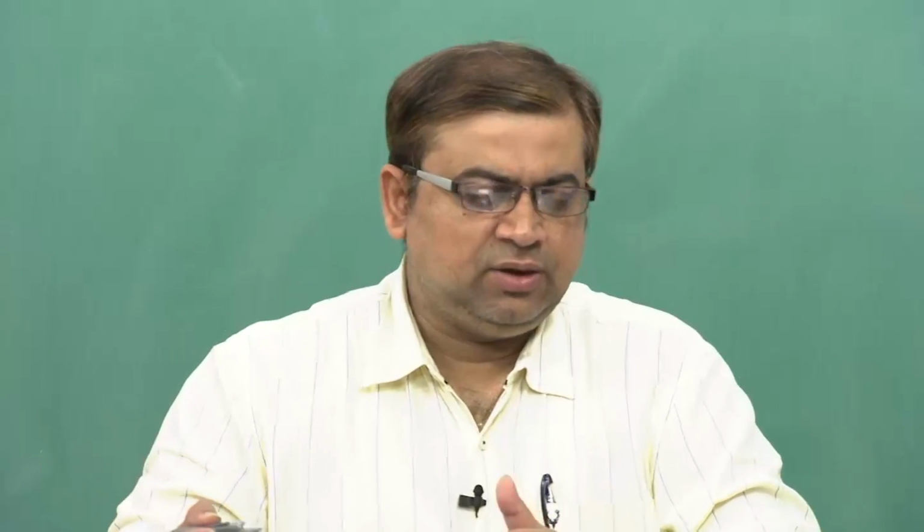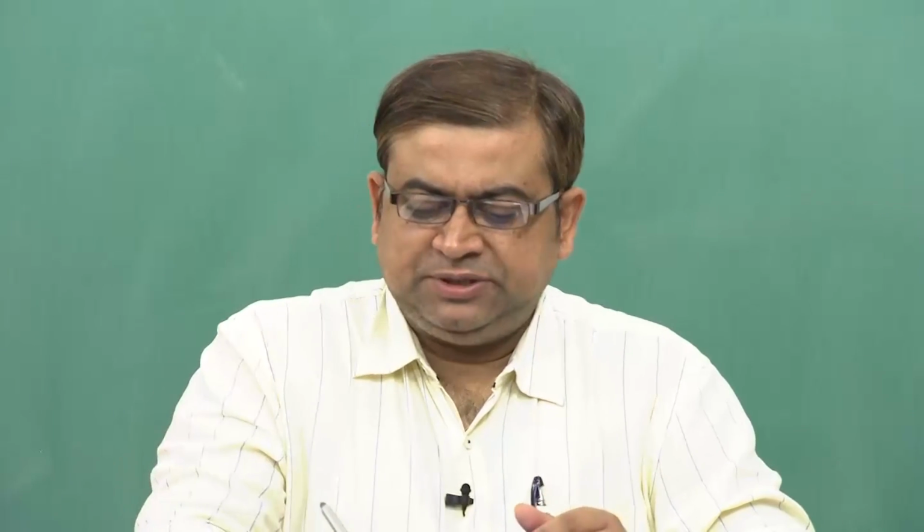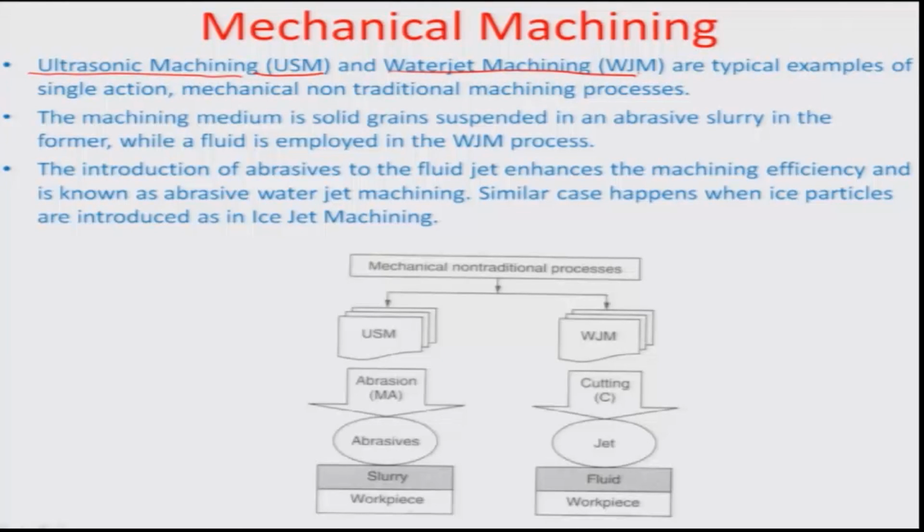Typically, this form of machining is highly preferred when we talk about ceramic machining or glass machining. We have water jet machining, where there is a jet of water at a very high velocity and very high pressure, which comes out of a small nozzle and is loaded with abrasive particles. So, there is always a possibility of the abrasive particles being thrown upon a surface, which would again create a brittle fracture process, and that is how cutting is performed.